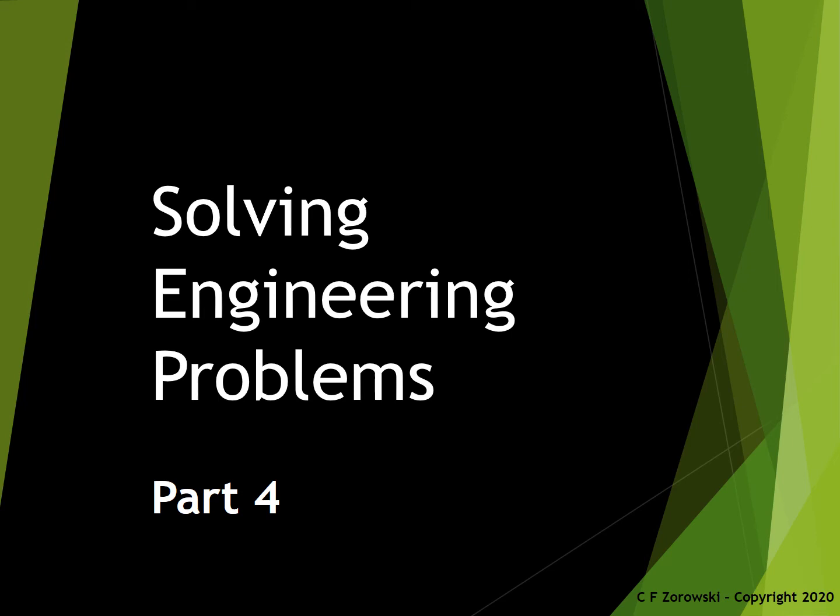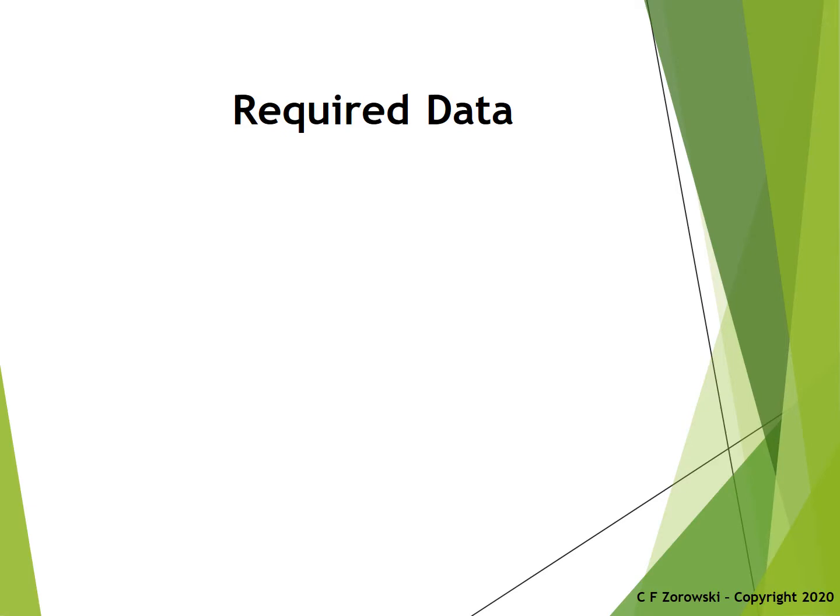Part 4, the solution of the transmission shift problem is extended to answer the questions not resolved in Part 3. Do the optimum shift points occur at the same engine speed for power and torque, and how are these speeds determined numerically? To obtain answers to these remaining questions, quantitative data is required for all system parameters dealt with in Part 3.